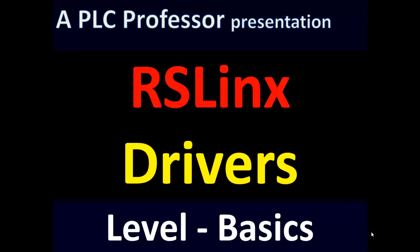Configuring an RSLinx driver, whether it's for a PLC5, a SLC 500, a Micrologix, a ControlLogix, a CompactLogix, FlexLogix, the process is identical. An RSLinx DF1 driver is an RSLinx DF1 driver. Ethernet devices driver, because remember that these drivers drive a port on your personal computer, and that port is connected by cable to a like port on the controller itself.